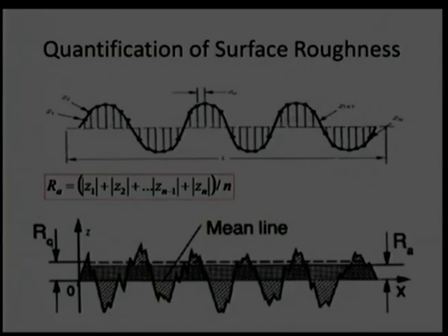As earlier mentioned, there is another surface roughness parameter which is preferred in the tribology division or tribological applications, the RQ value. An interesting thing is that the RQ value will always be higher than the RA value. That is good from an application point of view. We are taking a more conservative approach, and as I mentioned earlier, we penalize peaks.